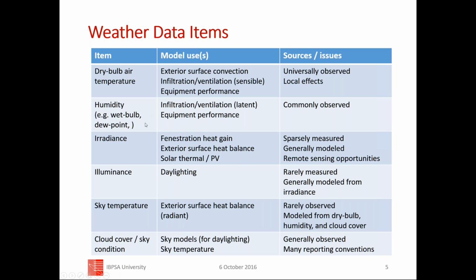Humidity is measured either as wet bulb or dew point, or sometimes relative humidity. Those are interconvertible by software, so any one point will work. You need that for latent transfer and equipment performance, and these are commonly observed.